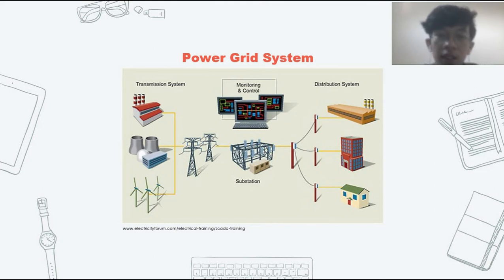Then it is branched and distributed to distribution substations through a medium voltage 20 kV channel, and low voltage 220 volt. The distributed voltage depends on the type of customer, which is divided into several groups, from small industry, light industry, office to housing.